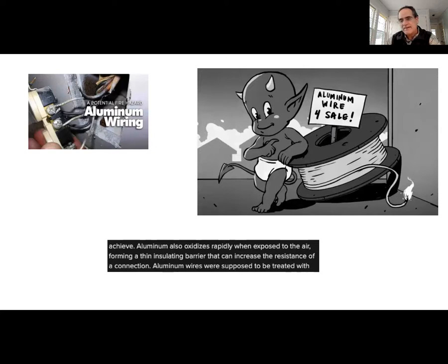And as it gets thicker, the resistance of electrical connections between aluminum wires starts to grow. When we pass a large current through that, there's Joule heating, and eventually the Joule heating might be enough to ignite the flammable aluminum wire. So, lesson learned, I guess, but an interesting application of tunneling.